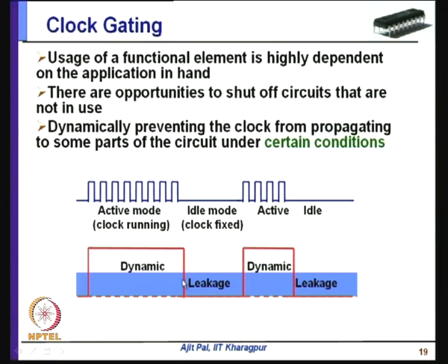As you can see, when clock is not gated, then you have got dynamic power dissipation as well as leakage power dissipation. However, when clock is gated, you have got only leakage power dissipation, not the dynamic power dissipation. Therefore, there is significant reduction in power dissipation that will take place whenever clock gating is done, and we have discussed how you can really achieve clock gating in different parts of the circuit.